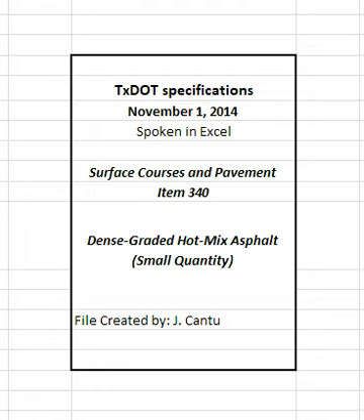Table 1. Aggregate quality requirements. See table in specifications. 1. Not used for acceptance purposes. Optional test used by the engineer as an indicator of the need for further investigation. 2. Only applies to crushed gravel. 3. Aggregates, without mineral filler, RAP, RAS, or additives, combined as used in the job mix formula, JMF.